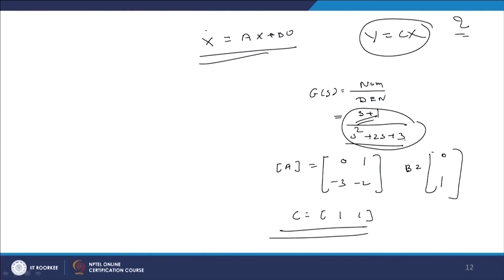So, when the zeros have not been utilized in the controller design, definitely when we determine the actual performance, this may create some problem to our system performance. Therefore, there is a need to tackle these issues. So, in the next part we will see how to handle the effect of zeros, or in other words how to handle the effect of the C matrix in controller design.